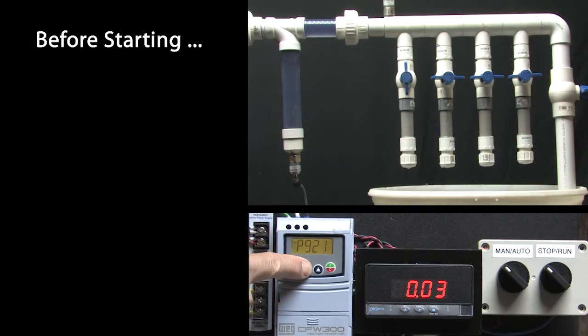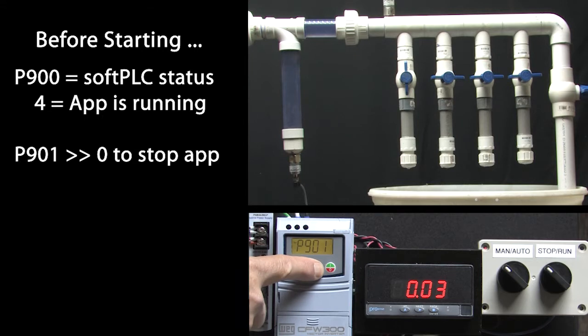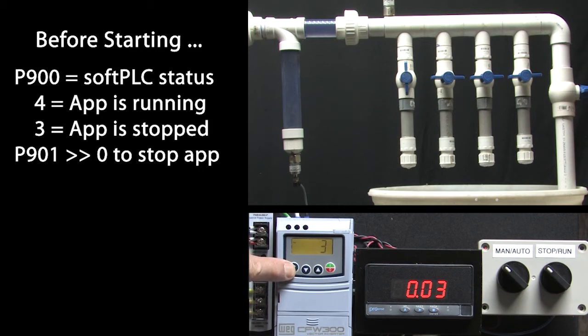Now before starting, go to parameter 900. A 4 says an application is currently running, so I'll go to parameter 901 and set it to a 0 to disable the soft PLC. Go back to parameter 900, and we see a 3 which tells us the application is not running.